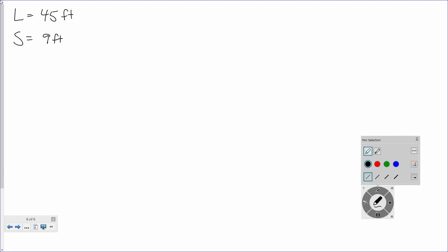Now, if you recall that KLL, that's a live load element factor. It's the ratio of the tributary area to the influence area, okay? Now, are we looking at a column or are we looking at a beam? Beam. So what's KLL? 2. All right? So let's keep going. All right.